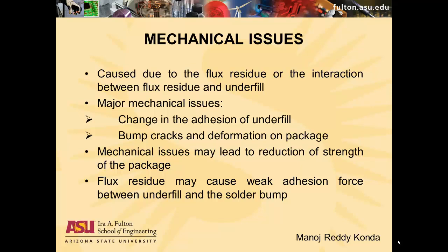Thank you, Vivek. Now we are going to discuss the mechanical issues due to the flux residue. Several mechanical issues are induced mainly due to the flux residue or due to the interaction between the flux residue and underfill. The major mechanical issues that can be found on the surface of the flip chip package are changes in the adhesion between the underfill and the solder bumps, seeding of bump cracks, and deformation of bumps.